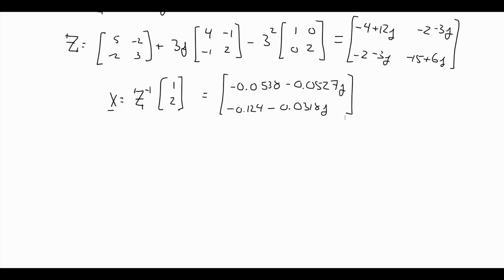So what I want to find is what I will call x1, I'll just use a superscript, but that's just talking about the first degree of freedom, and x2, the second degree of freedom. And I want their phases, I'll call phi1 and phi2. So again, this is just going to come from complex algebra, finding the angle of each of these entries for phi and the magnitude of each of these entries for the x values.